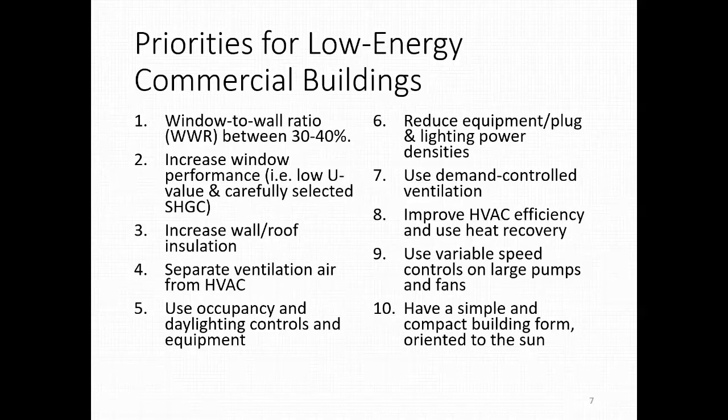For instance, if you do like 2x8 walls or something like that, and you have thick batt insulation, if you use an air permeable insulation and you don't wrap your building tightly, your air control is not well done. You'll get what's called wind washing, and you will get air currents inside of your walls.